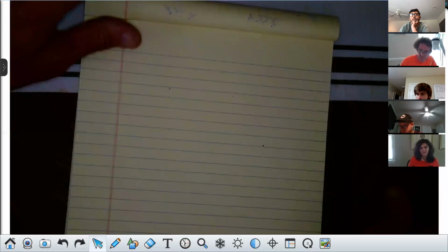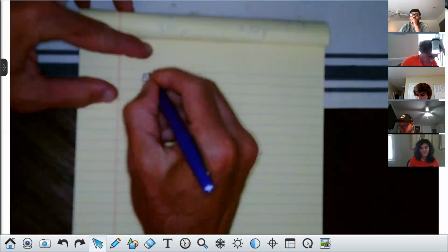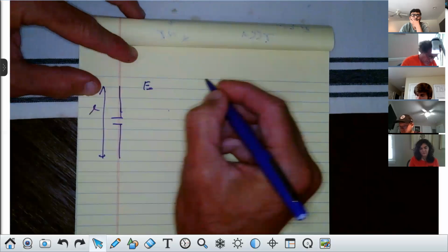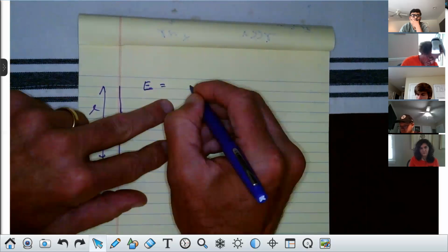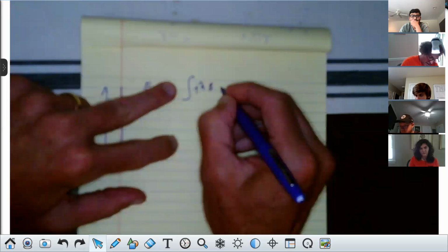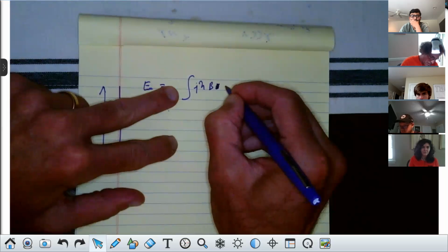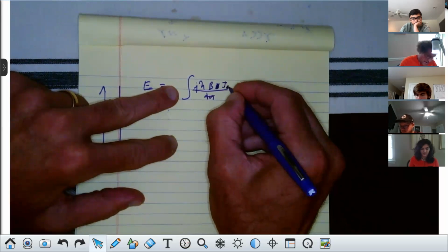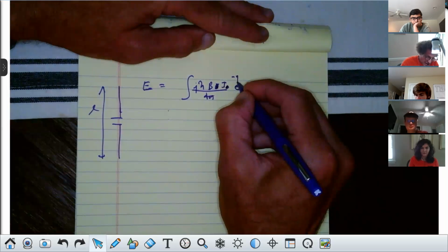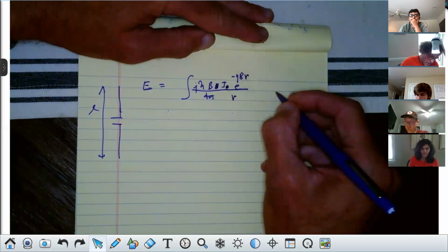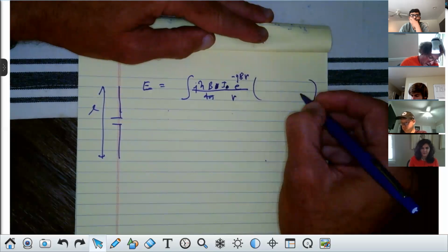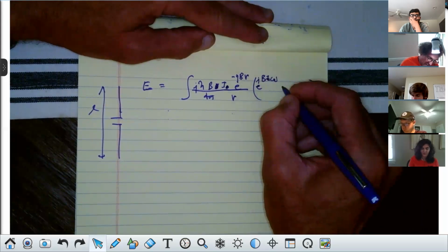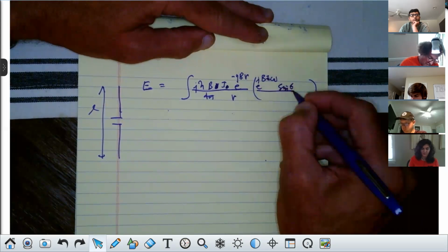Now I'm going to say that the total E field, and this is for an arbitrarily long dipole on the z-axis, again, a dipole on the z-axis of arbitrary length L that has the current I gave you in the prior one, that E would be equal to the integral of j eta beta over 4 pi, then I naught, that's the magnitude of I, and then e to the minus j beta r, 1 over r, and then the last part, e to the j beta z cosine of theta, times the sine of theta, times dz.